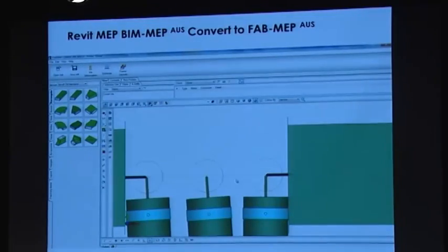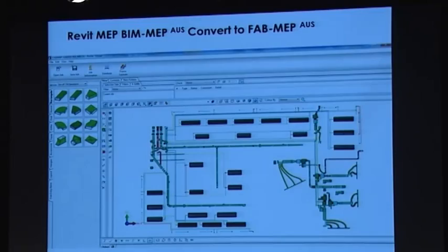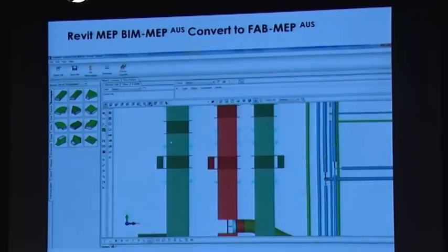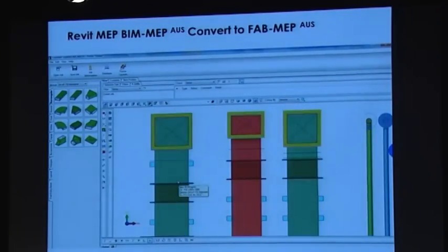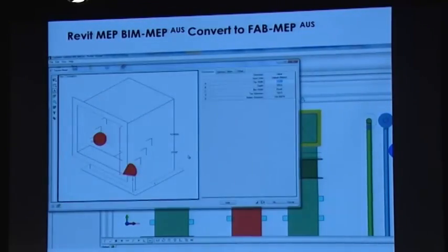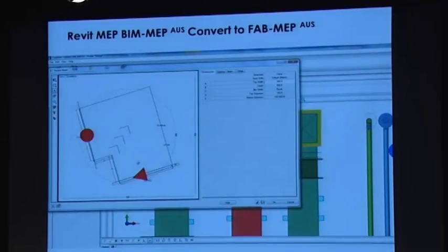You'll notice here I've got some taps. They're not right-angled taps, so you can't put a tap on a rectangular duct and expect the software to auto-calculate that. There's a lot of auto-calculating going on here. You've got hangers created automatically. The connectors are auto-estimated, which we saw earlier, and that fitting now is detailed content for fabrication.